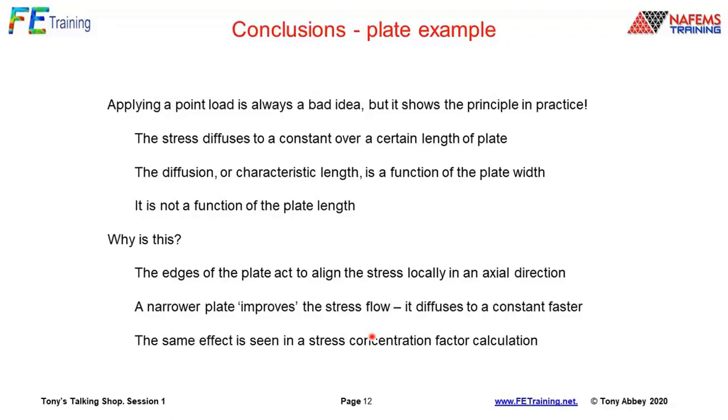Now, the counter to that is that as we narrow the plate, the nominal stress goes up. So we've got a stress concentration factor of 3 times perhaps a low stress, and then the stress concentration factor perhaps drops down to 1.5, but the nominal stress has gone up because our net section is bigger. But it's the same kind of idea, same kind of effect. So something to think about. I like to think about stress flowing and the way that the stress flows.